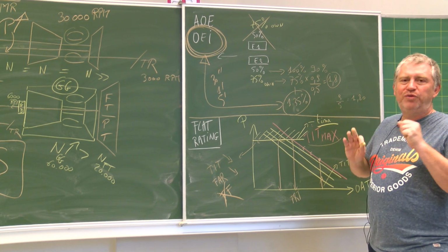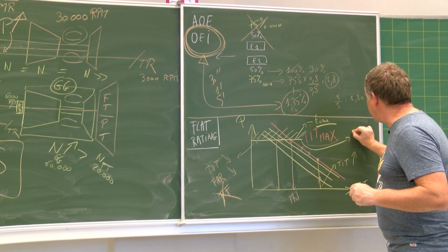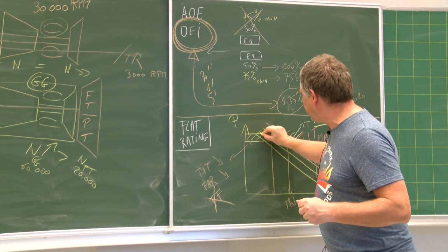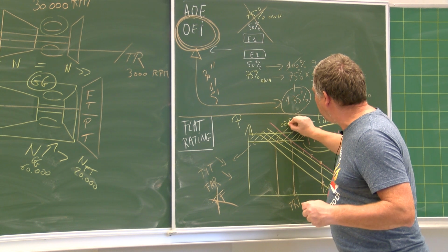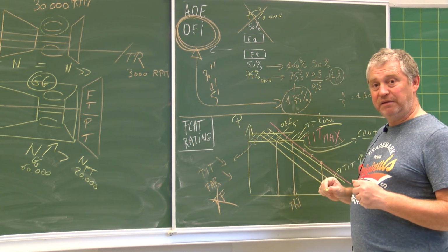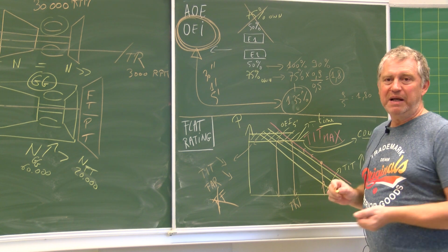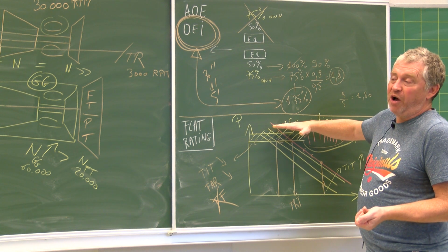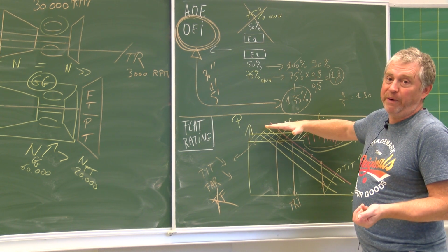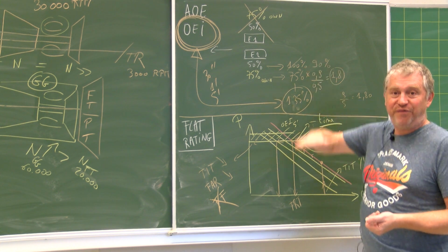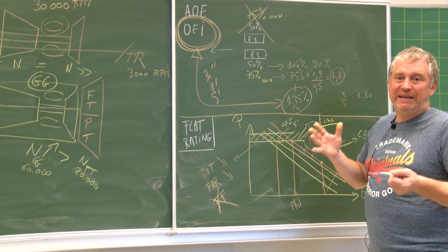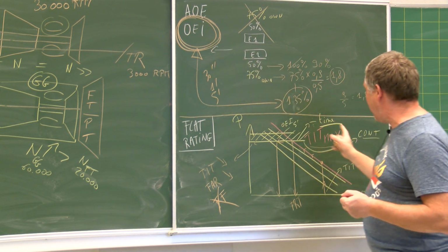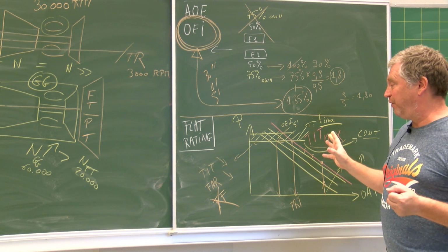So if this is, for example, continuous operation, and you want to fix the OEI 5 minutes here, this is certainly possible, because you decrease the time during which you will operate, so you will have also different flat rating limits, depending on how long you are staying in that situation. That's why I've discussed the OEI before discussing the flat rating.